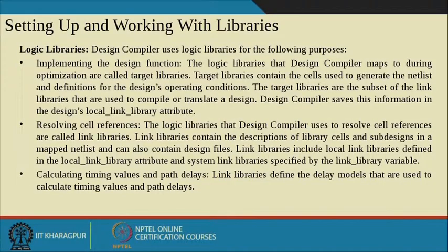The logic library is where the information about the basic gates will be. Using link underscore library we can specify that library: this is my logic library, so please link to this particular library.